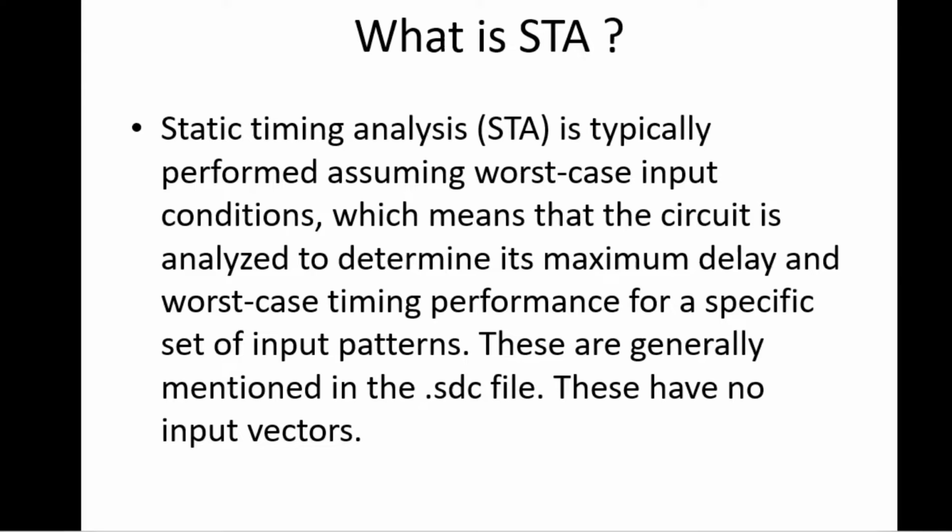I'm just introducing the worst corners. What are FF corners and SS corners? I'll show you those slides also. I'm just making notes, you can note these points: SS corner for setup analysis and FF corner for hold analysis. Just for information.